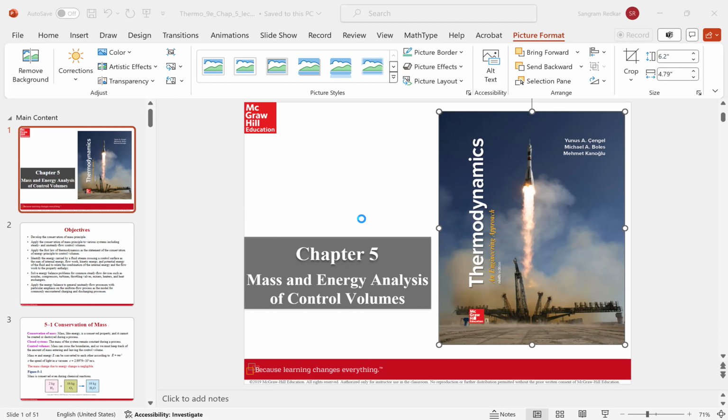If you look at these fighter planes when they go supersonic, those converging nozzles become diverging nozzles, and the plane changes shape, because the control surfaces that allow you to control at subsonic speeds cannot control when you achieve supersonic speeds. So at subsonic, things are different. At supersonic, things are different. At subsonic speeds, you have converging nozzles. At supersonic speeds, you have diverging nozzles.